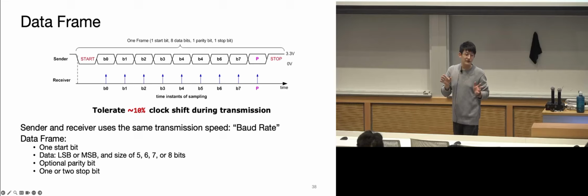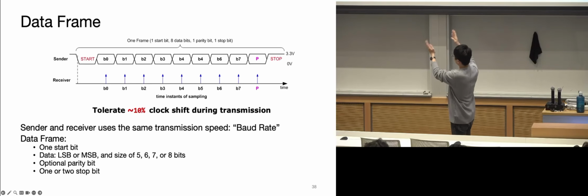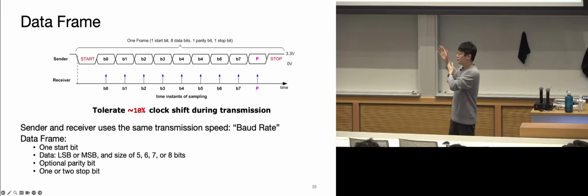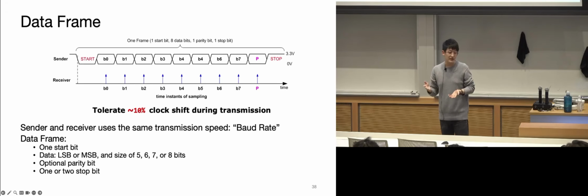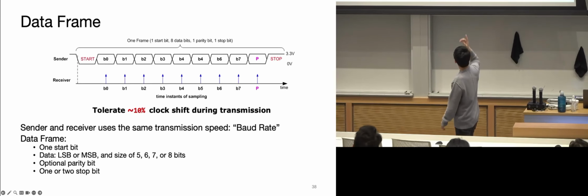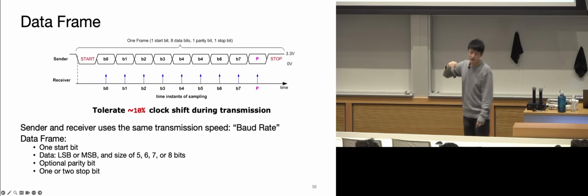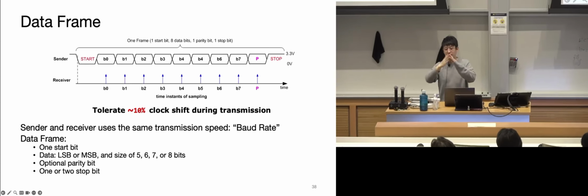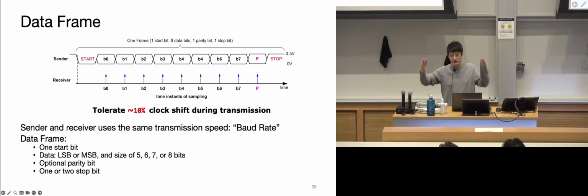You can choose your configuration, but that's the amount of bits for each data sent. The reason they chose that is to match the ASCII numbers. They also have an additional optional parity bit, and then a stop bit, 1 or 2 bits depending on the configuration, to fill in the block basically.